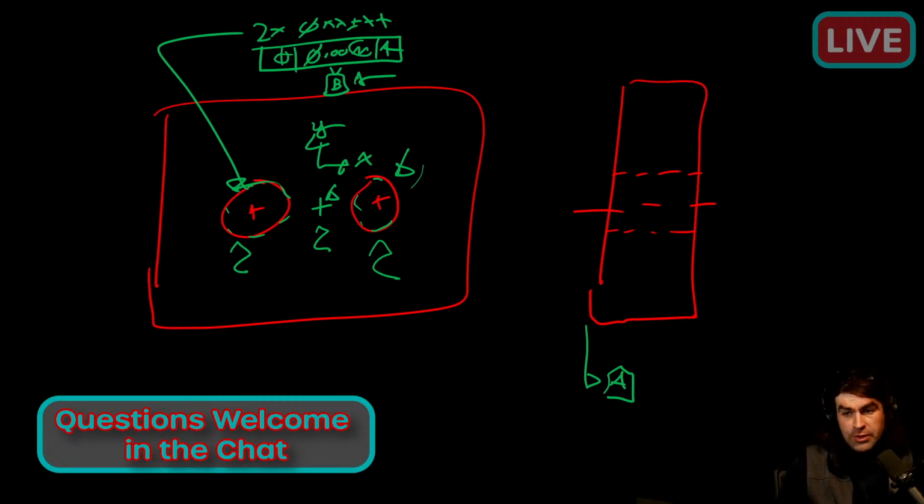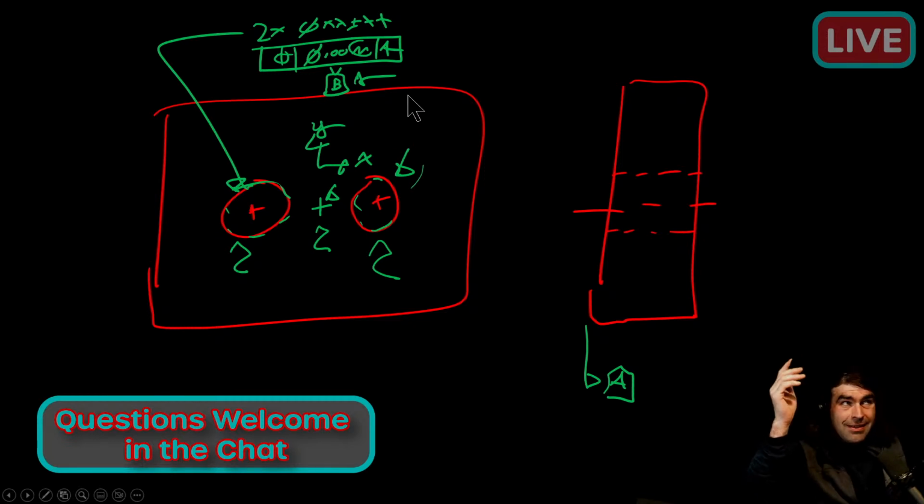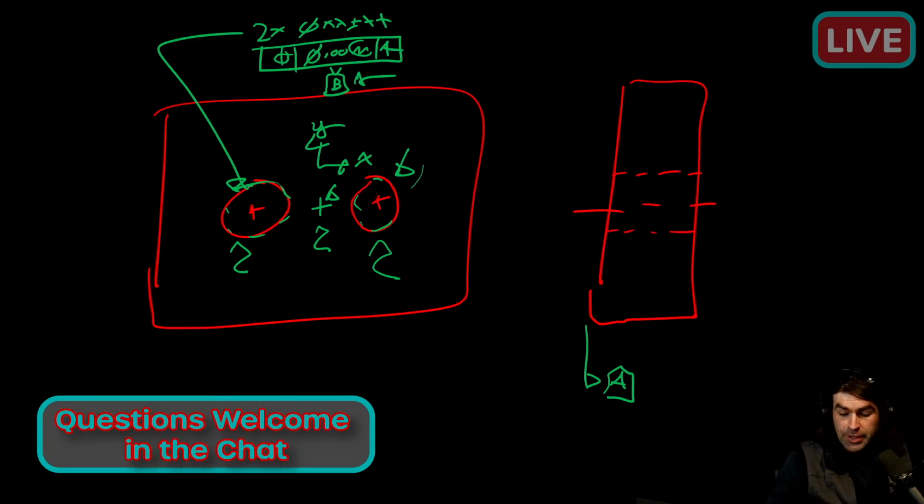So another question would be, hey Mark, would least squares be a useful datum approach for surfaces that might wear or break in? That's a super interesting question. If you hop on SolidWorks, the latest version, and their feature control frame wizard or whatever, there's dozens of things you can put in there, and I'm sure they're all ISO. They're not ASME, I can tell you that. But yeah, you can put in LSQ and all sorts of acronyms for fitting algorithms, which is pretty cool.